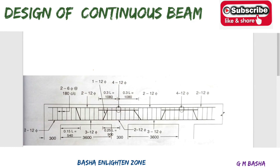See here, this is the beam that I explained now. There will be 4 bars of 12 dia at the supports and 3 bars of 12 dia at the interior supports and the mid spans. See here how the bars will be provided. If you see here, 2 bars of 12 dia.